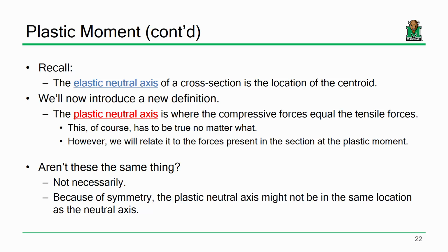It's the area of steel times Fy. What's my compressive force? 0.85 f'c times A times B. And you must determine the depth of that stress block such that C equals T. That is essentially a plastic neutral axis. We're going to do something very similar here.